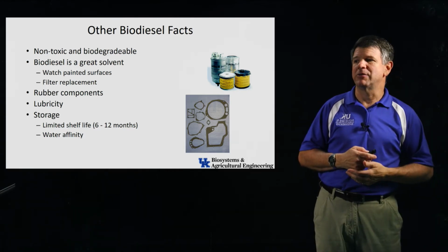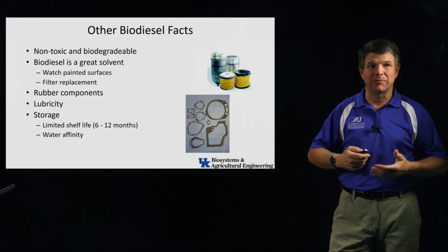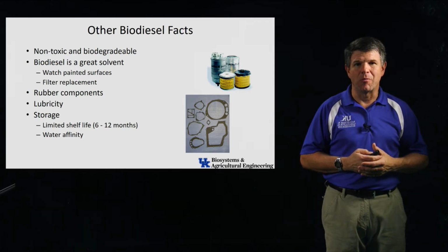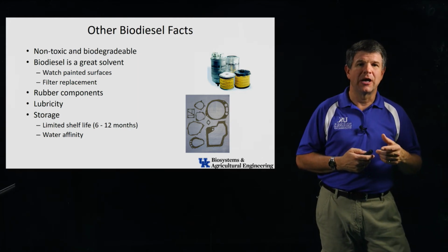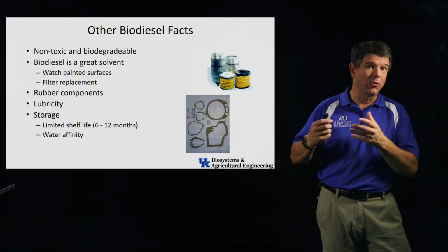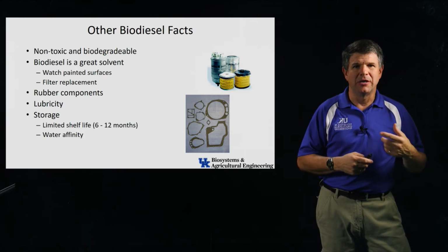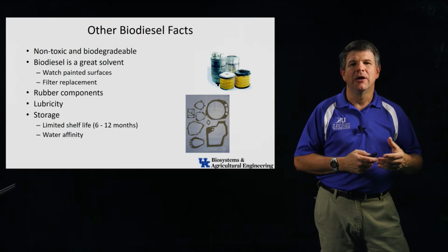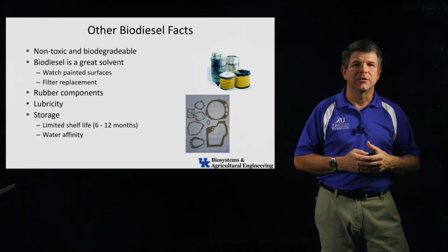And we always have to think about storage, how long the fuels will last. So sometimes you can keep fuels for a long time. Some fuels won't last very long. They'll go bad. They essentially oxidize, like a piece of metal will rust. Some oxygen in the fuel is good, we talked about that with the combustion equation, but too much means it's not going to be a good fuel. It's not going to have the power, not have the energy content, and actually may not burn very well. And so we have to watch that.